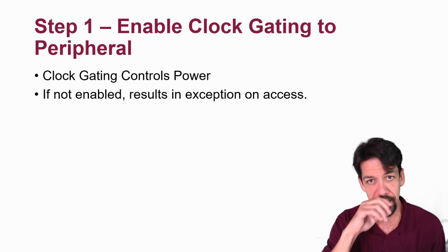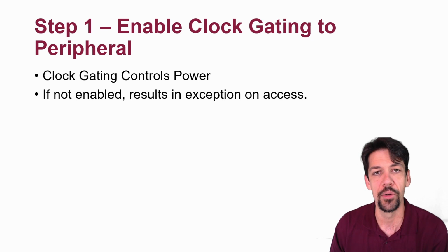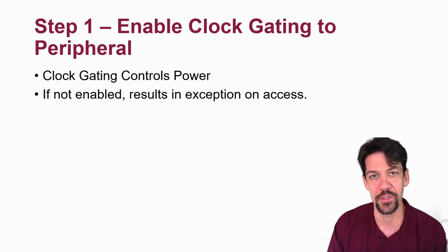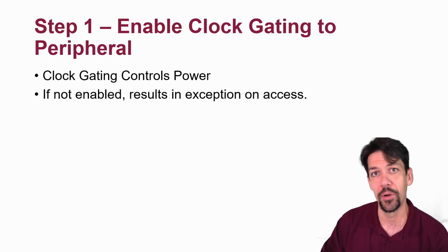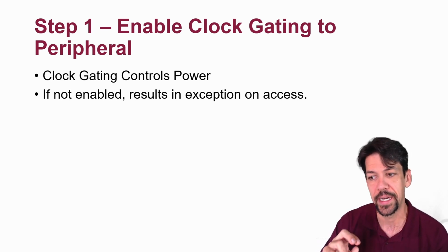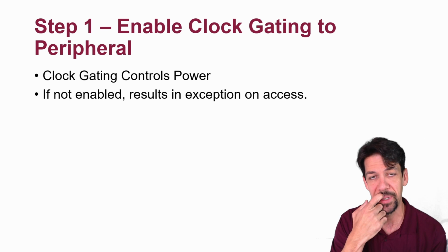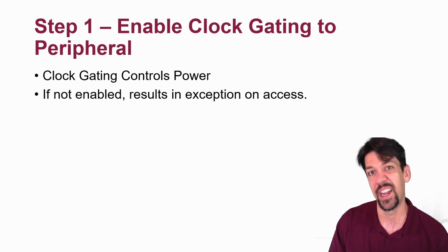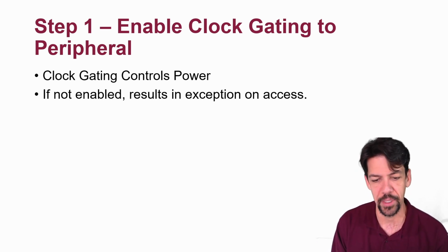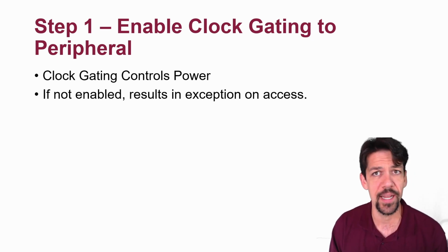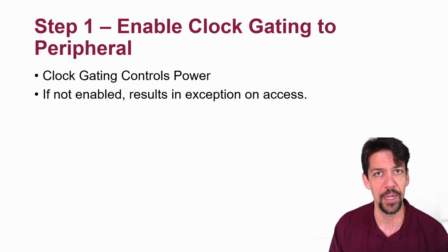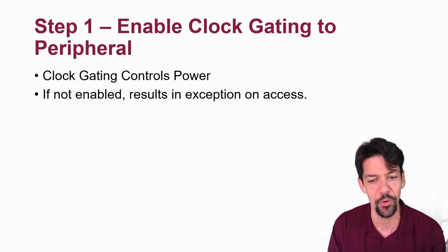You'll get an exception in the compiler in debug mode. It will throw an exception and pause the program. When running not in debug mode on the microcontroller, you'll get an exception and the processor will drop into an exception handler and hang, and nothing will happen, right? So your program won't run at all. And this will be a runtime exception. Your program will compile just fine, but it'll be a runtime exception and something will go terribly wrong.